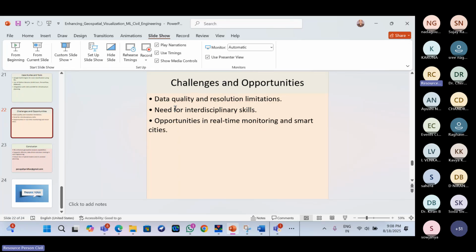Actually, suppose in any hydrological assessment study using a SWAT model, we have to input land use land cover, digital elevation model, and soil map of your study area. Later, we have to provide the weather parameters with the locational information only.